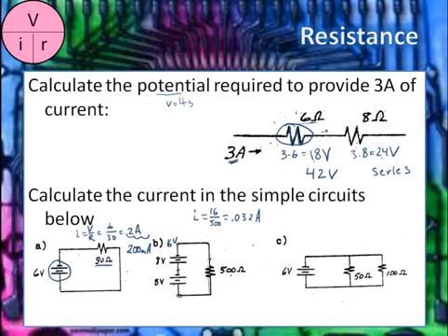And down here, these two resistors are set up so that they're both attached to the same wire at the same voltage of 6 volts up here and 6 volts here, and it leaves and has 0 volts down here. But these two resistors are parallel to each other, what we call in parallel. And we'll talk about the difference between setting up resistors in series or in parallel, and why you might want to do one versus the other, in a future video.